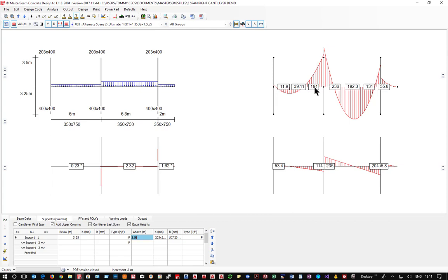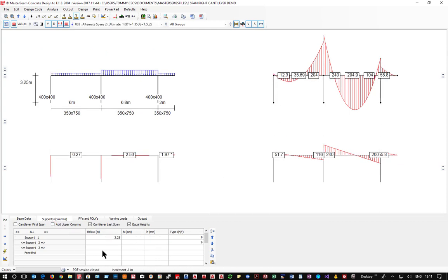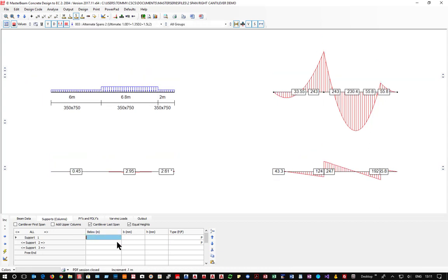So we're getting 194 and 237, so they're not symmetrical because some of it is being resisted by that column. So take out my columns and the forces start to change, and take out the height above and the force comes down and it evens itself out instead.